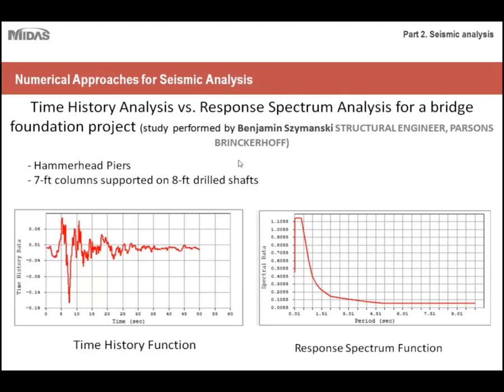Okay, so now let's take a direct comparison of time history analysis versus response spectrum analysis for a bridge foundation project. This study was performed by Benjamin Szymanski from Parsons-Bergerhoff. He's a bridge engineer, but he decided to do a study of how response spectrum analysis and time history analysis differ as far as the results are concerned in his particular bridge project. Here it was a hammerhead pier, 7-foot columns, supported on 8-foot drill shafts.